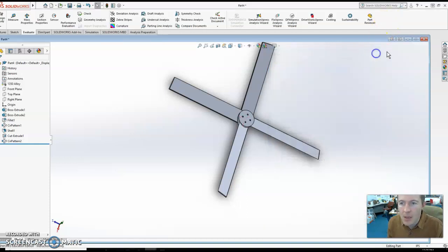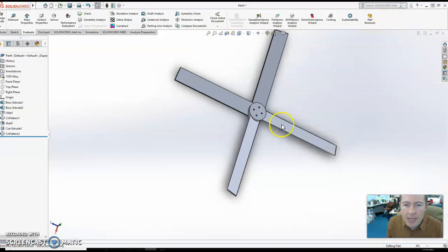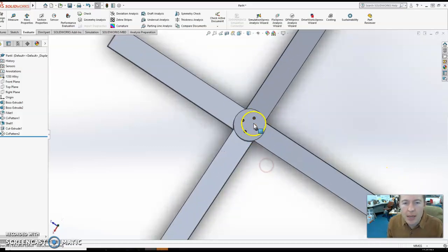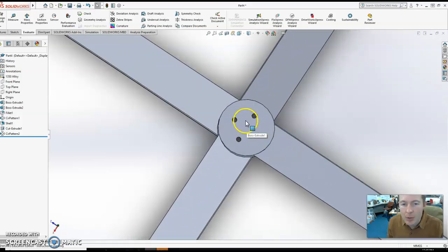That looks great. Now let's say I actually needed this in metric rather than English. So down here in the little corner, I can change our units to whatever we want. If I click this, I can click usually millimeters, grams, seconds, click that, and now if I were to, let's say I needed a part right here, now it's operating in millimeters and grams.